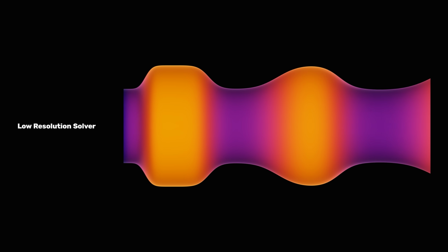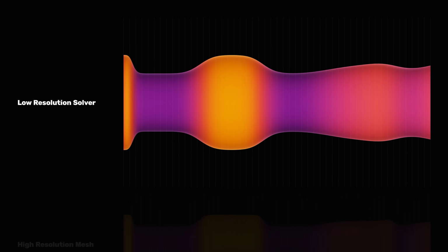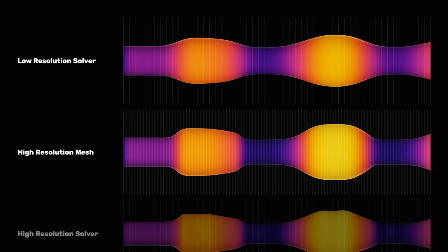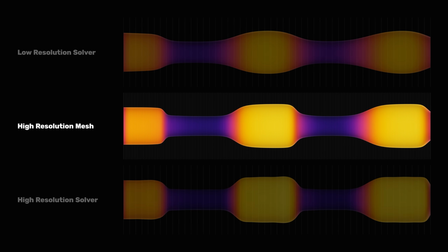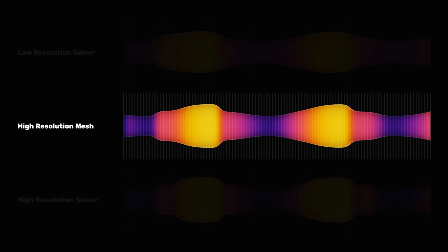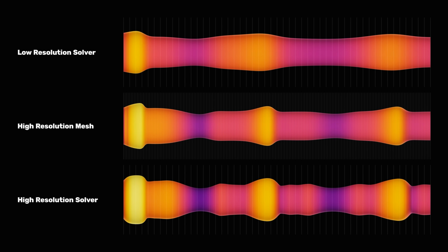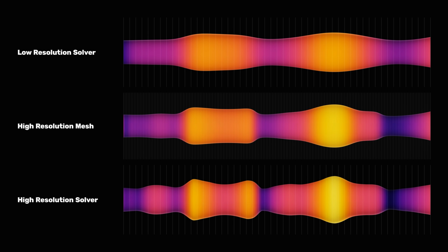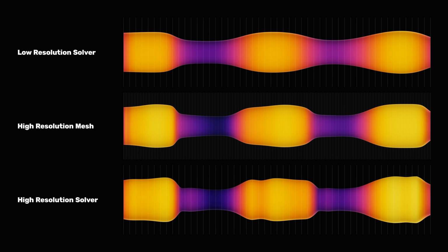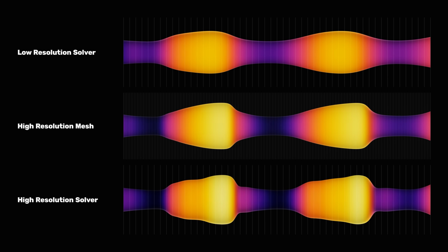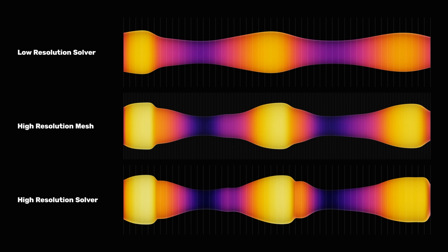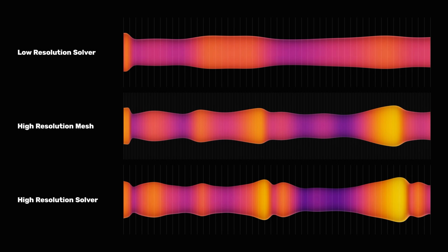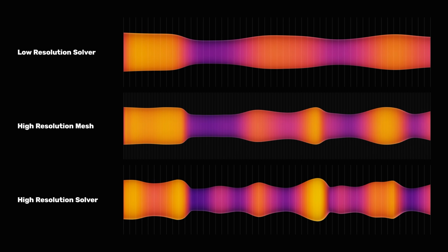There are two main techniques we can use to rectify this. We can either subdivide the simulation into a finer grid, or we can just use a better solver. The first option is simpler, but requires more computation because we need more cells. But since the method is cheap, it doesn't seem like such a big deal. However, for complicated reasons, the performance cost actually grows non-linearly as the resolution increases, quickly making this approach impractical. Brute forcing a bad technique into producing sharp output obviously isn't ideal, so we'll instead look to more advanced methods.